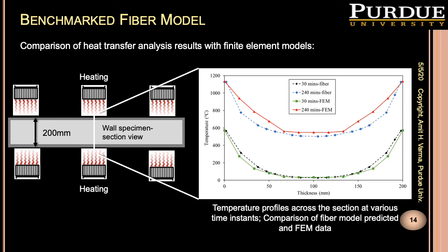This slide compares the obtained temperature profile, at zero wall thickness, from the fiber model and finite element models at 30 minutes and 4 hours of heating. The obtained temperatures from the fiber-based heat transfer analysis are in good agreement with finite element results and experimentally measured temperatures.